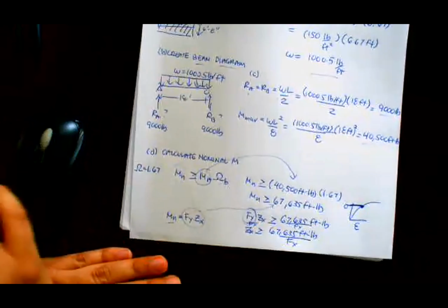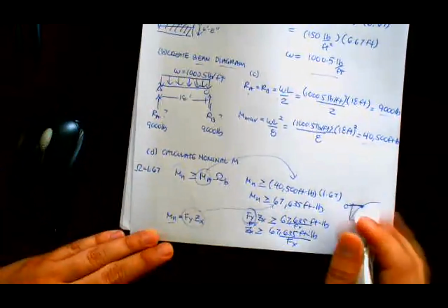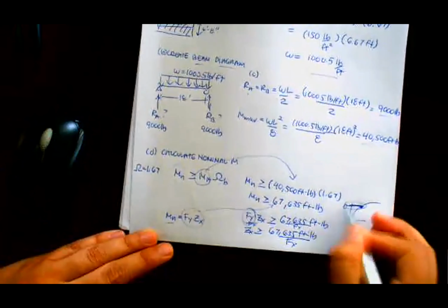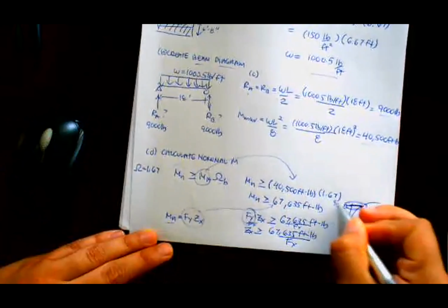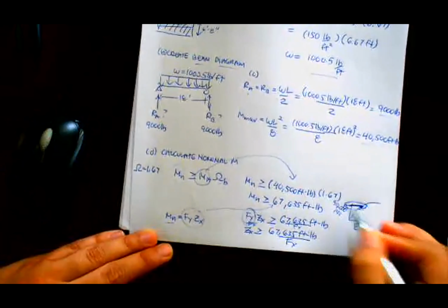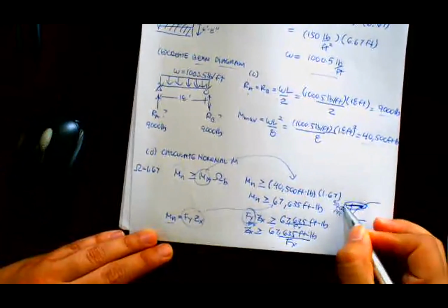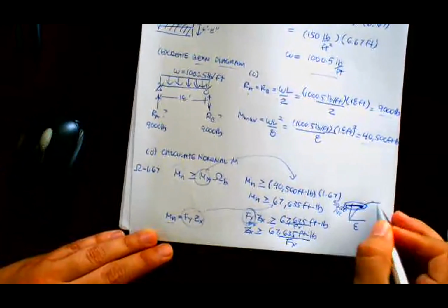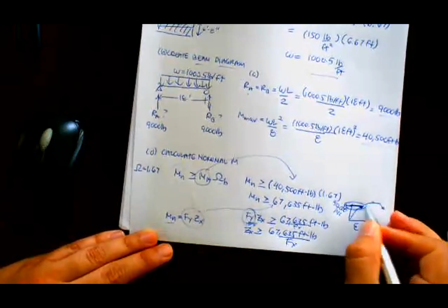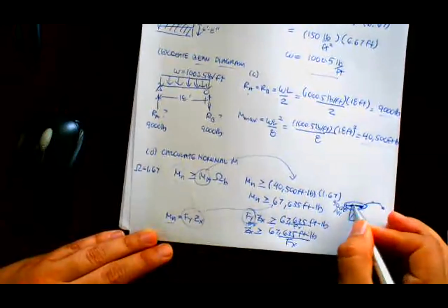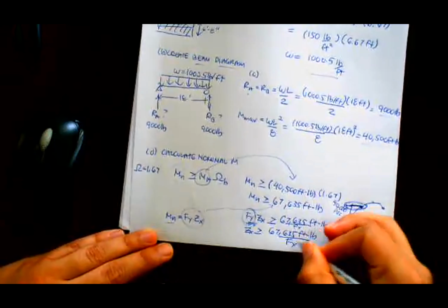And you've got to understand, 50,000 psi, exactly 50,000 psi, which means that if I'm looking at my graph, this point right here is 50,000. It means that at the yield point, the stress is 50,000 for steel. It doesn't mean it's the ultimate. It doesn't mean it's the failure stress. It means it's the yield point, and that's what we consider failure. So I'm going to replace this with 50,000.